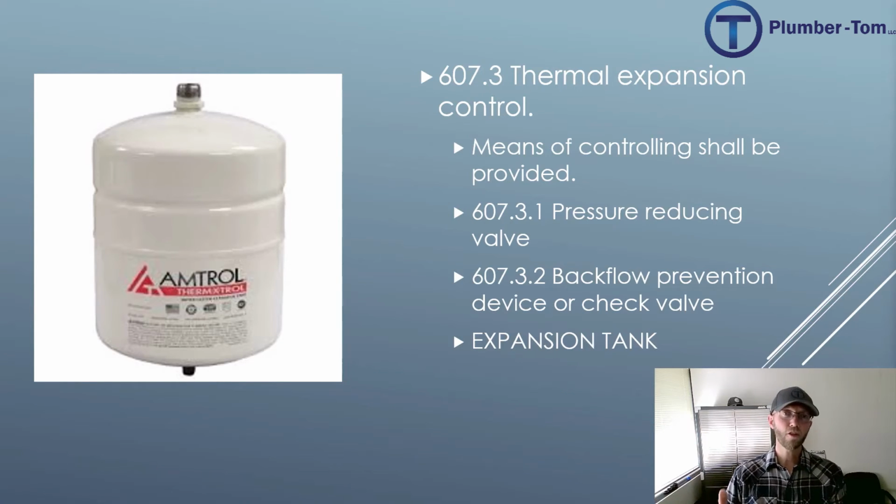This becomes particularly important in a system that is closed, meaning that water comes in from the city and then it passes through a check valve or a pressure reducing valve or a backflow preventer, and it can't go backwards, so the system is locked. Now all the water that is in there is stuck. As the water heats up, of course, it drives the pressure up, and that is bad for everything in the system: valves, faucets, and especially water heaters. The code says you need to make sure that your expansion tank fits the size of your system, particularly that it can handle the amount of water in the system and the size of your water heater.